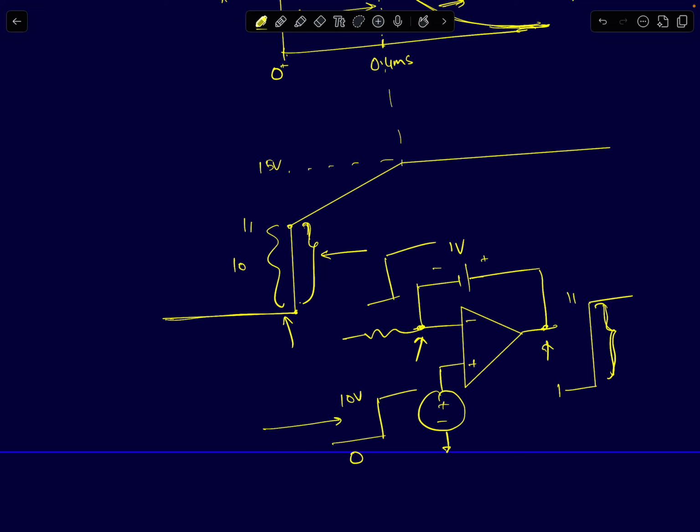Because at that instant, incrementally, it's just a voltage follower. Incrementally I can ignore the source resistance of the 1 volt source, since the incremental resistance is 0. So if I short circuit this, delta V should be the same. The capacitor is modeled as a voltage source of 1 volt at that instant. The only difference it will make is where you start off.